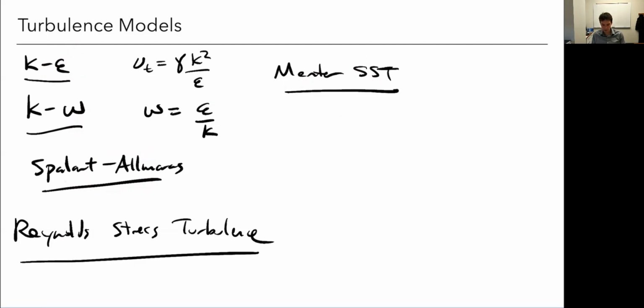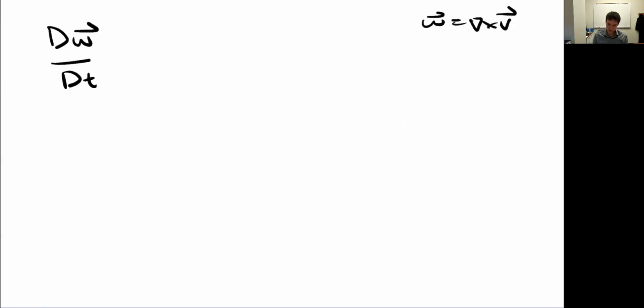Let's see, maybe I'll talk about this briefly. Last sort of concept. I'm not going to derive this, but there's the vorticity equations where I take the Navier-Stokes equations and I take the curl of the equation. And I'm not going to write the whole one, but let me just write the shorter version where I eliminate some of the terms if I assume that it's a constant density, like so incompressible. Then omega, remember omega is my vorticity. So I took the curl of the whole Navier-Stokes equation. And so, I'm going to get, instead of velocity terms, I'll have vorticity terms.